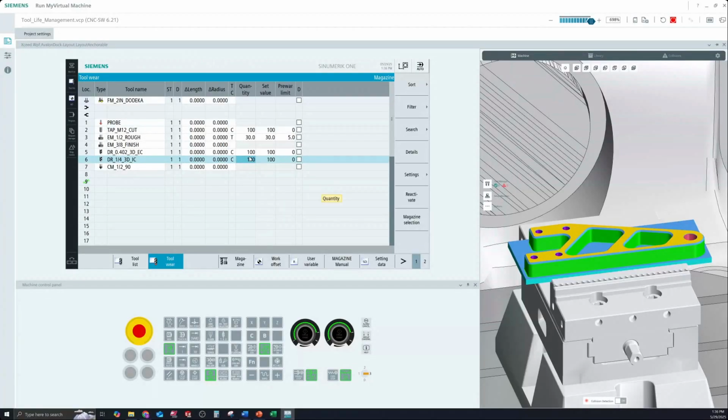It's not like if I run my program and it reads an M30, it's going to count down to 99, 98, 97, and so forth. It's not going to count down anything unless I put something in the program that tells it to count down for every tool that is set to count. Now, let me show you what I mean.